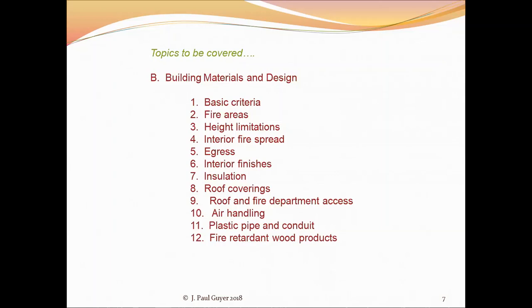And this vertical pipe, a fire department riser, a fire riser, at each floor has a T and a valve and a fitting so that the firefighters can connect their fire hoses at, say, the 5th floor to the T-fitting in the stairwell typically, and then go and fight the fire on the 5th floor or the 6th floor or wherever it happens to be.